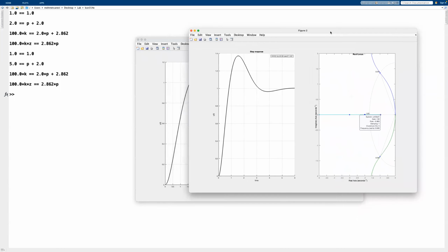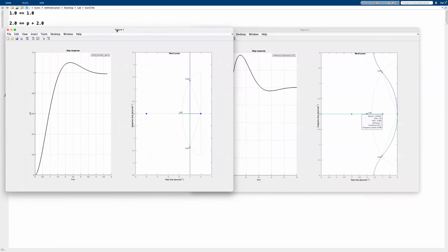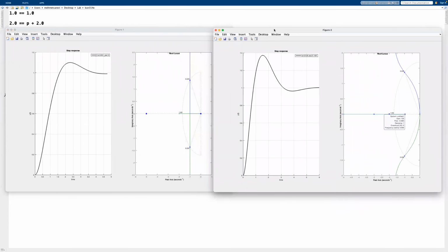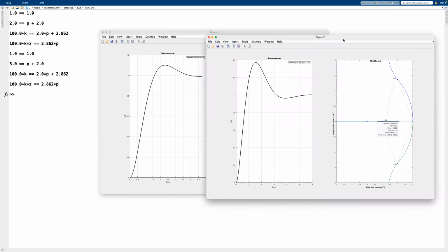Canceling poles and zeros, of course, fixes the structure of the PID controller, and that's not always a good thing. You can see that on the right we have a bad example, and on the left a good example. Here, this one works, but it is not a PID controller, it's a PD controller. The PID controller is not the best one that we are looking for.